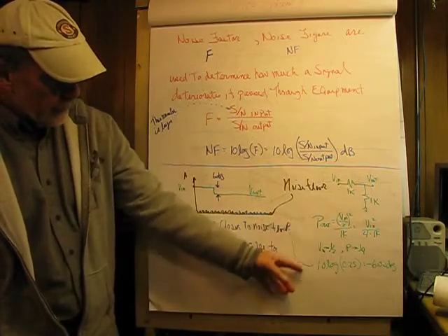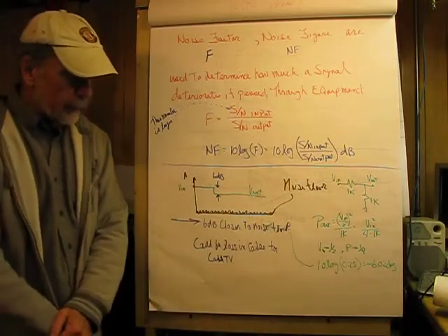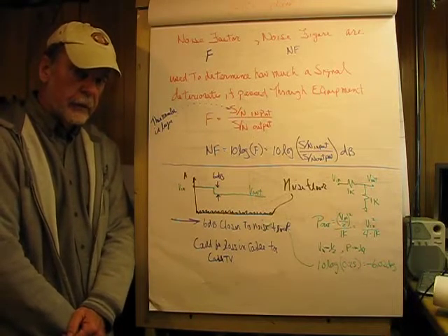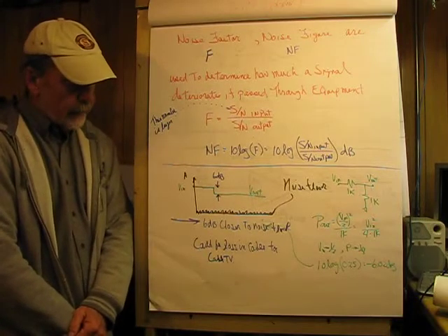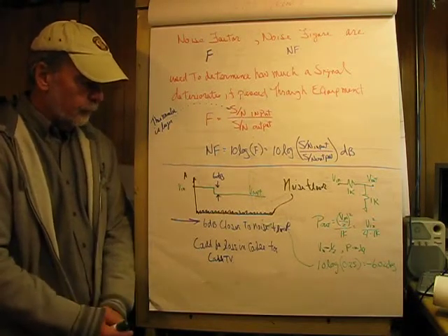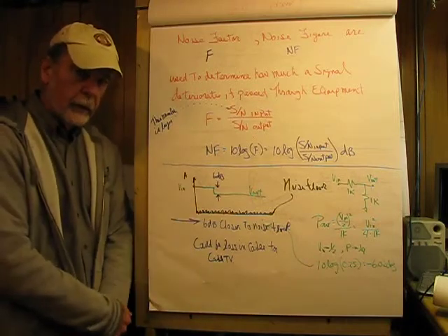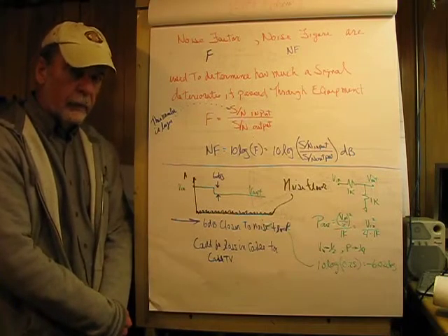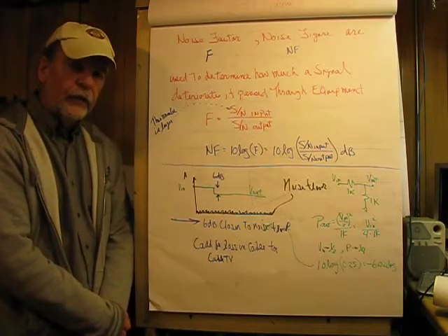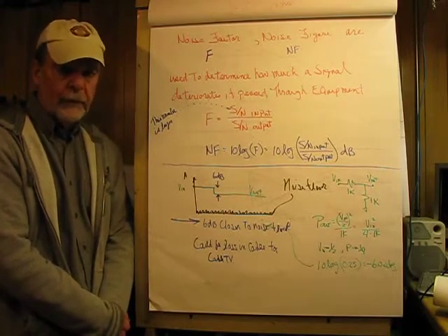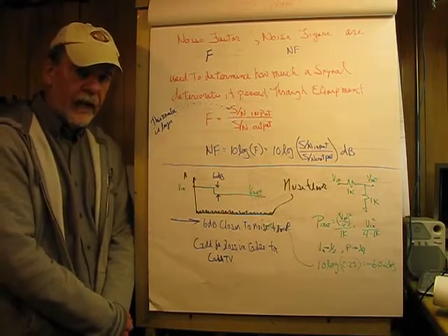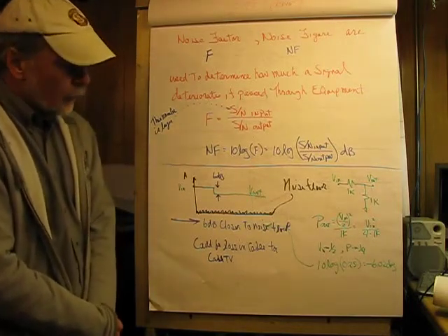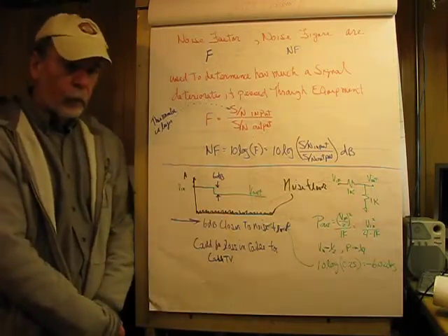Now if I go down and take a look at that here, in the log domain, I see that 10 times the log of 0.25 is equal to -6 dB. So if you have an antenna on your house and you're wiring it into a room, and you do not have a mast-mounted preamplifier, you could lose 6 dB in the cable. If you have a cable TV system with a splitter with 4 spigots, each spigot is down by 6 dB plus a little more. There's additional loss in there. So a little model here represents some real-world stuff.